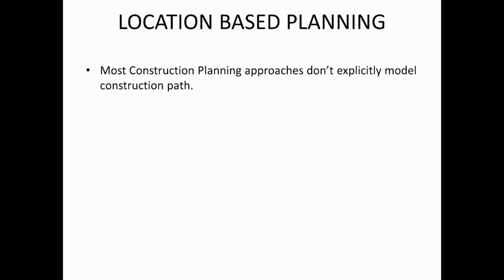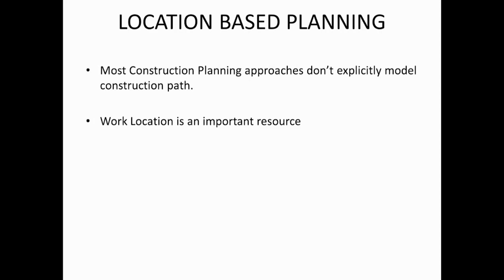When we go into location based planning, so far when we did CPM, we did not take location explicitly into account. We did not talk about what the construction path is going to be. We just talked about activities and started solving for activity based times. We looked at early start, early finish, and resources, but location and space is also an important resource.